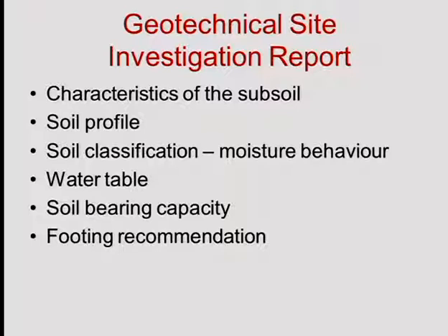Oh, actually, near the end of Bourke Street extends. Next time you go to Docklands, have a look at where the car parks are. There are no underground car parks in Docklands. Why is that? Because the Docklands area was the alluvial plains of the Yarra River when it flooded. And the Docklands area is absolutely the worst soil that you can have to build on.